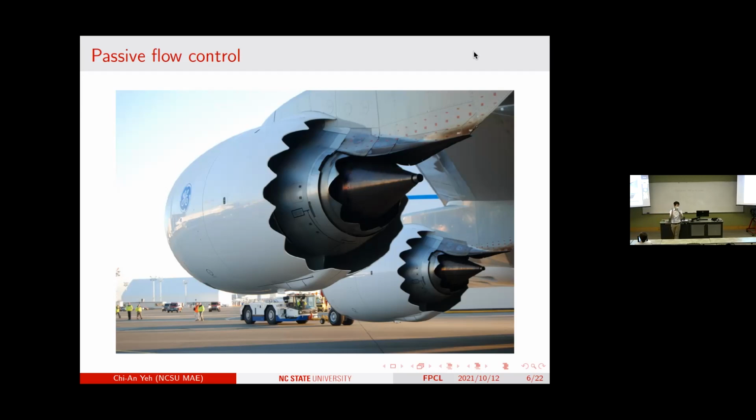And now they dump this flow data into some sort of data analysis tool. Now we're looking at a matrix of maybe 10 million by 10 million. They pull out the eigenvalues and eigenvectors, and according to the eigenvector, they choose, hey, this is my optimal circumferential wave number I'm supposed to throw in when designing this engine.